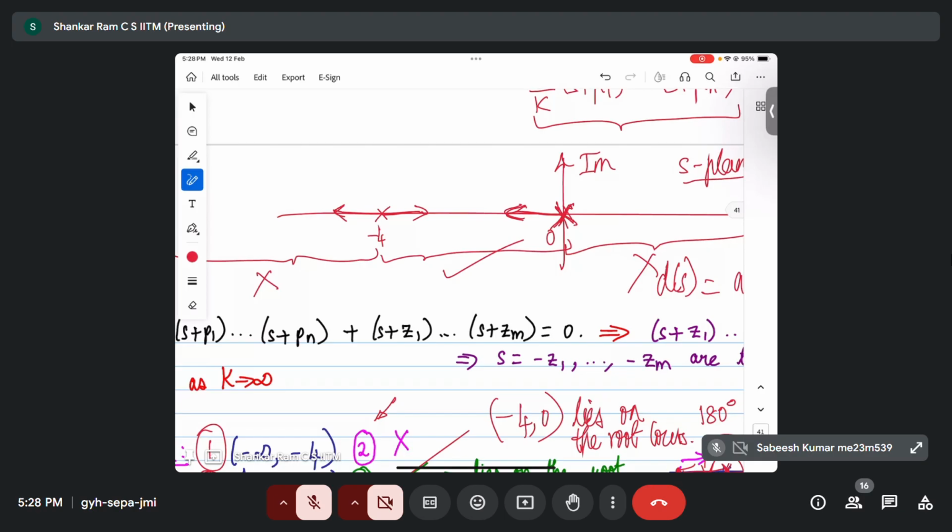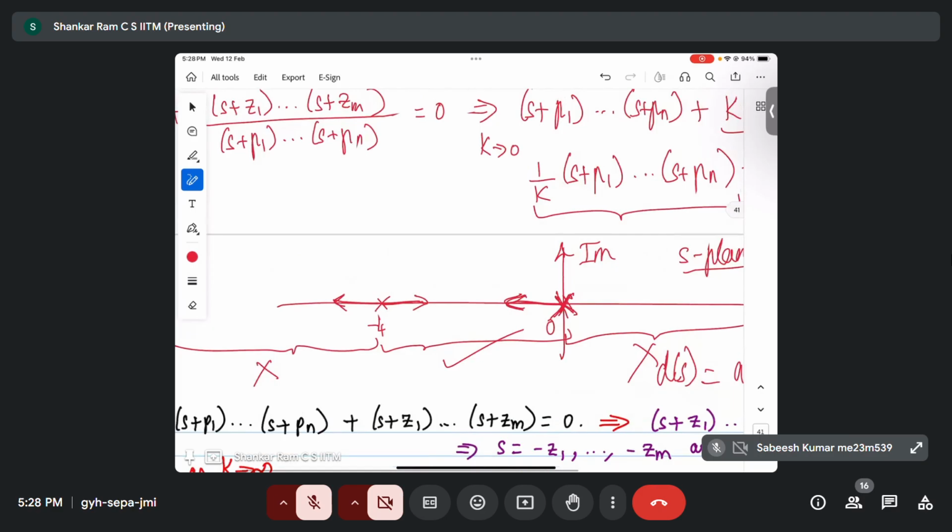I will ask in a different way, sir. We are saying there is only one pole at -4, hence the conjugate roots cannot appear. Will there be any possibility where complex conjugate branches exist? Absolutely, even in this example we are going to look at that. To answer your specific question, let's say we have a system with a repeating open loop pole at -3.